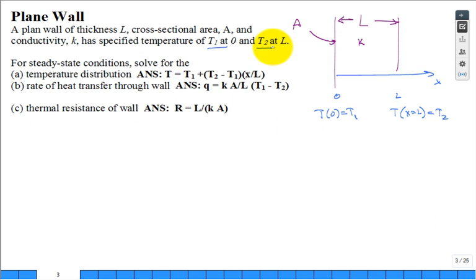Okay, somebody says, I want you to solve for the temperature distribution as if you're the first person ever to do it. Set up that governing partial differential equation, turn it into an ordinary differential equation, two boundary conditions, separate, integrate twice, and lo and behold, not to insult you, but there it is. You want me to do it or not? Please. Okay, well, here's our governing differential equation. Second derivative of temperature with respect to space is equal to 0. Was that not our governing differential equation?